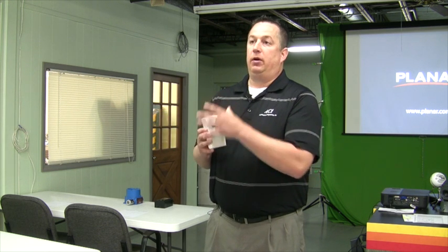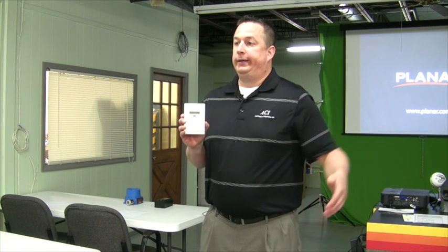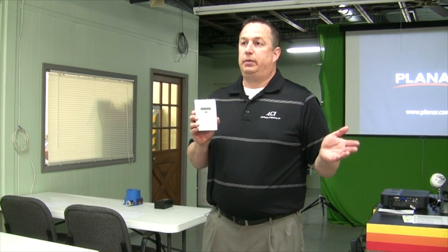Now this is the wall mount shown here. We also have it for a duct mount that basically comes with a tube out the back and a NEMA rated enclosure. I also mentioned we do have this in outdoor air sensors now for CO2. In the past, you would just maybe put in your building automation system a value of 450 ppm.